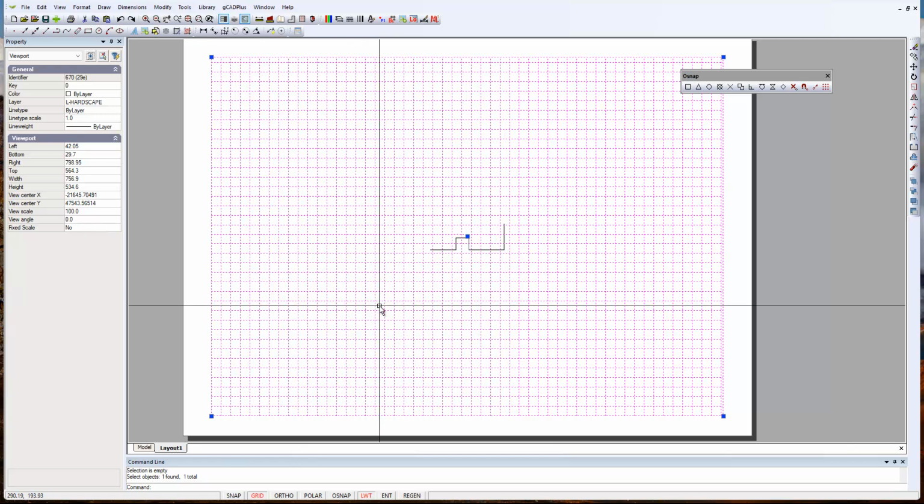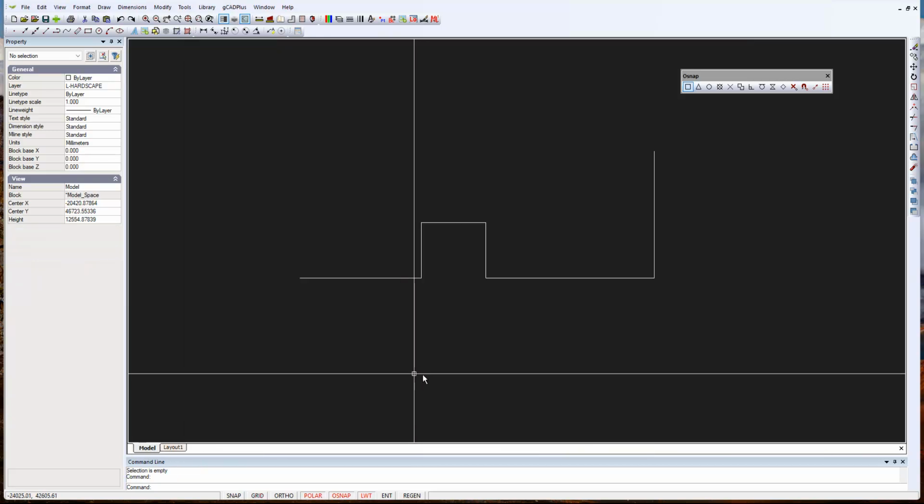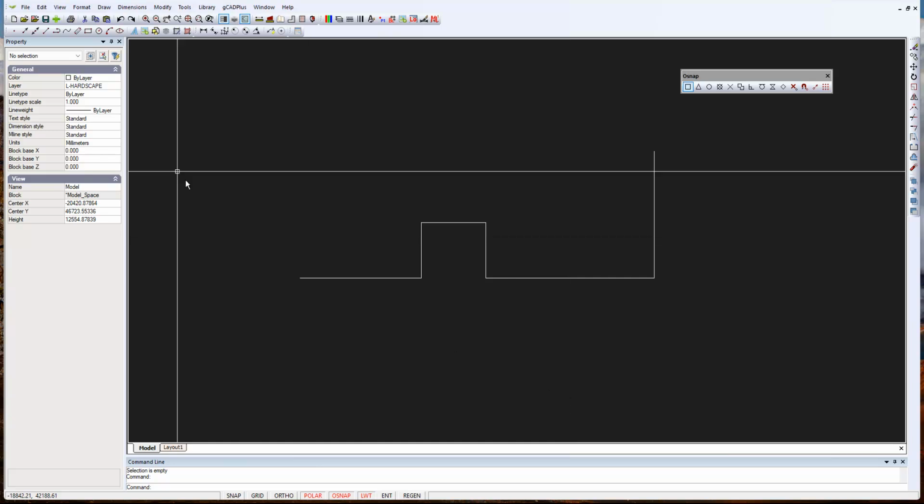We could fix that if we like, because one of the questions we're always asked at this stage, well, how do I print to scale? Well, you set your scale with that floating viewport and then print it 1 equals 1, and whatever prints out will be at that nominated scale. But most of our drafting, we won't come back to that layout for some considerable time. So we've progressed along in converting that mud map into our first landscape CAD drawing. Once again, keep on that habit of saving.